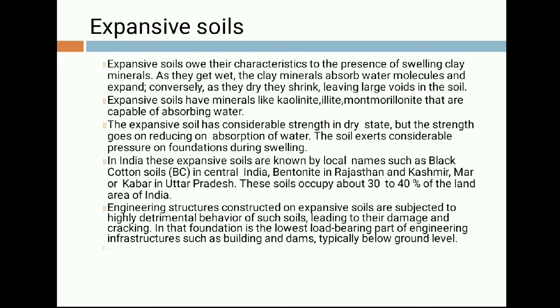Engineering structures constructed on expansive soil are subjected to highly detrimental behavior of such soil, leading to their damage and cracking. In that, foundation is the lowest load bearing part of engineering infrastructure such as building and dams, typically below ground level. Means not only the lower structure, that is your foundation, is affected because of expansive soil, but the ground beam or the ground slab or the exterior wall, even the interior wall, are affected because of the swelling property or shrinkage property of the black cotton soil.